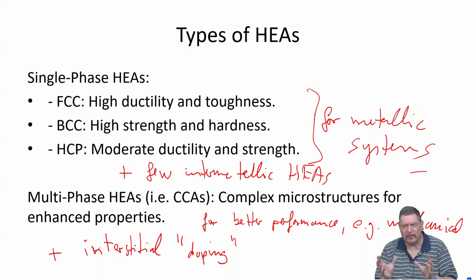So you have the other ingredients, nickel, for example, could be cobalt in it. It could also be some other transition metals. But then obviously one uses the experience coming from normal steel making in terms of using carbon, and mostly carbon, to produce alloys which have better properties, especially if one wants to go for transformation-induced plasticity or twinning-induced plasticity, TRIP and TWIP high entropy steels, and then you really need the carbon.